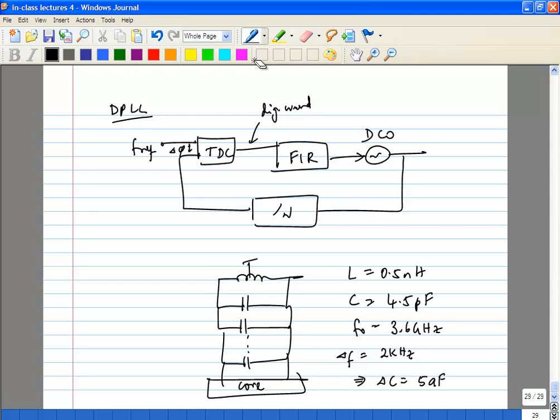These kinds of PLLs work very well when you have to do something special with the PLL. With normal PLLs, there is some RC variation, but you can try to compensate for it. You can design the PLL such that you take care of some amount of RC variation. But there may be cases where you want it to be very fixed.